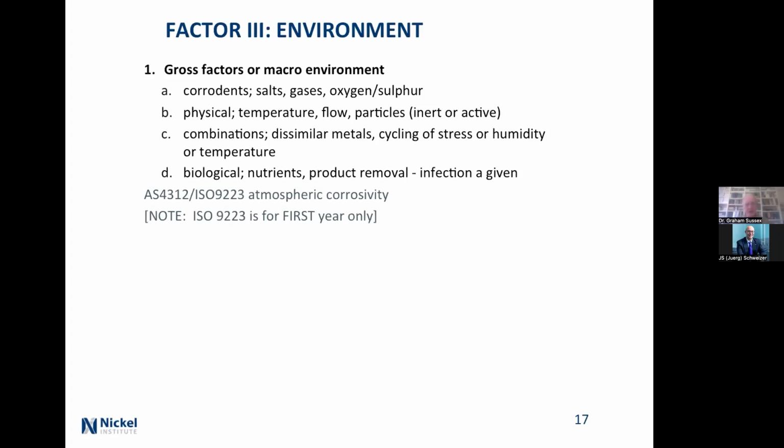If you're going above sort of 300, 350 degrees C, then you might worry about not using ferritics and not using duplex just because of metallurgical changes that can occur. And what sort of particles are around? Is there sand going to be abrading it? Or if it's in pipes, is there going to be particulate stuff to actually wear? And then what combinations have you got? Dissimilar metals. If you're putting aluminium against stainless steel, will it matter? And that's a complicated function of relative sizes, drainability, etc., etc. And then cycling of stress.